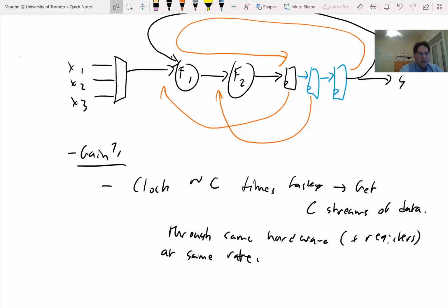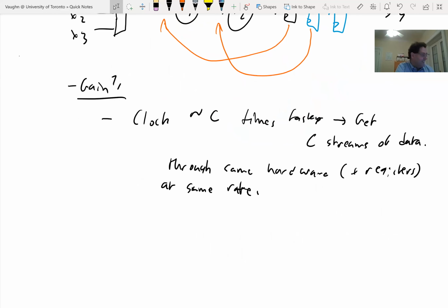And FPGAs are register rich, but they're not register infinite. So if you go completely crazy with registers, you'll eventually run out, right? So they'll start limiting the size of design you can fit in the chip. Anyway, that was a long answer to your question. Hopefully that answered it and was not annoyingly long.